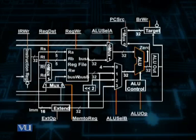For this purpose, as you can see from this diagram, register destination of the multiplexer 4 is made equal to 1 to select RD as the destination address. The memory to register is made equal to 0 to connect ALU out to the write bus, and the register write signal is asserted.